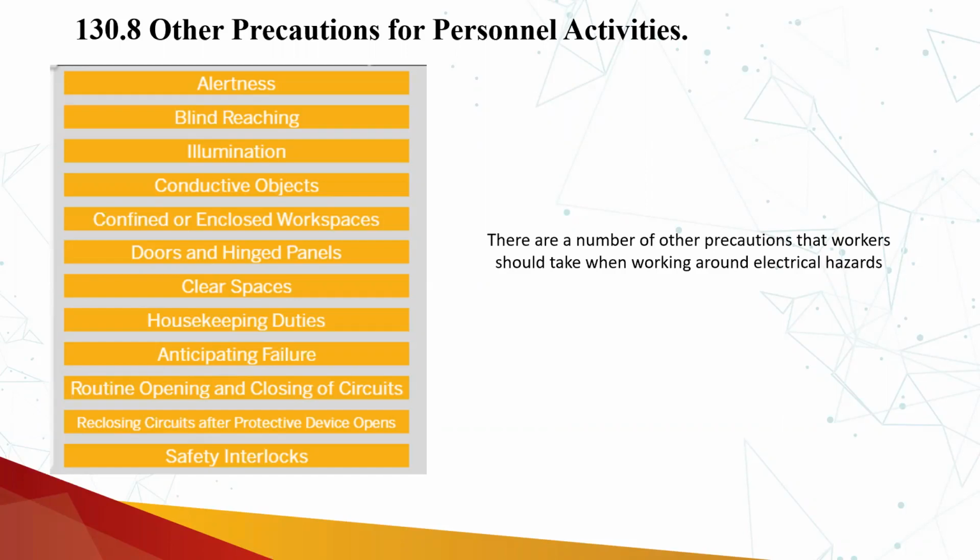In some events of an emergency fault, a qualified person who is working there can escape the area. If the clear spaces are used for storing or stocking, then that will come in the way, and the person will not be able to get out of that particular area safely.